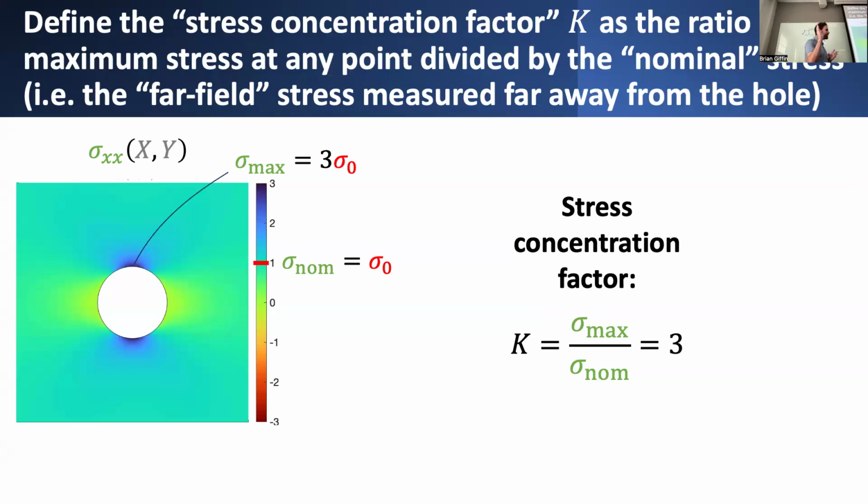Okay. Well, a stress concentration factor is really quite a useful tool, because at the end of the day, if all you really care about is not finding the solution to these complicated elasticity problems, which can be very time consuming and give you a lot of information, full descriptions of what the stresses look like surrounding the hole. But at the end of the day, you probably don't care about all that. As much as I want you to care about it, you probably just want to say, how do I design this? Or how do I choose whether or not to put a hole here?